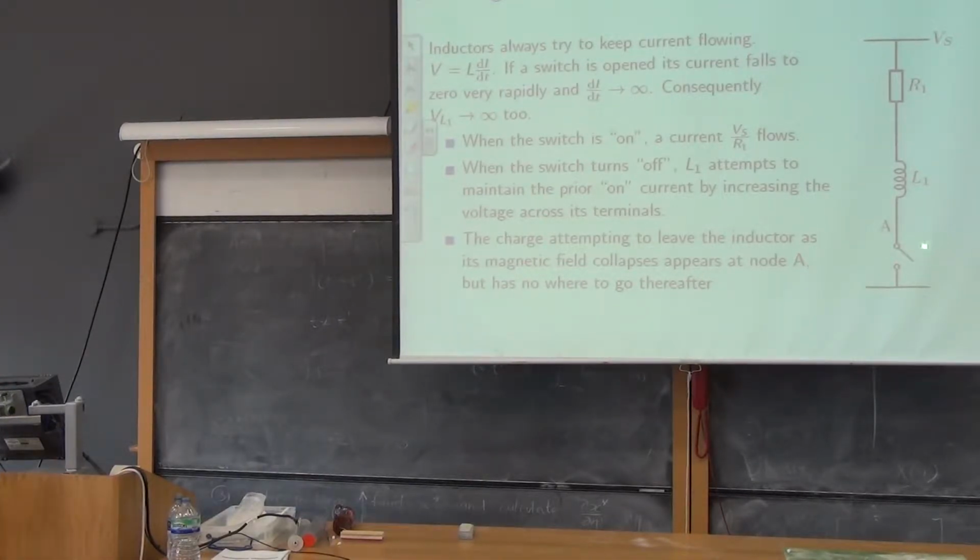When we actually open the switch, we've got di by dt in this pathway of infinite, because we suddenly open the switch and all of a sudden the current stops, and we'll assume that it stops immediately because it makes everything else that follows a bit easier. If that happens, we can apply V is L di by dt for the inductor, so there'll be a voltage generated across the inductor by this sudden di by dt of L times di by dt. But this is infinite, so V ought to be infinite as well. Happy? Unhappy.